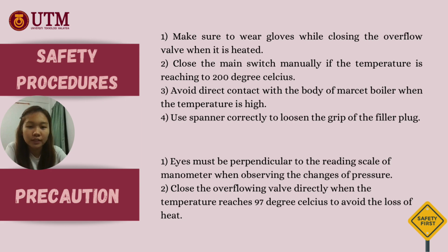Precaution. Firstly, eyes must be perpendicular to the reading scale of the manometer when observing the changes of pressure. Secondly, close the overflow valve directly when the temperature reaches 97 degrees Celsius to avoid the loss of heat.